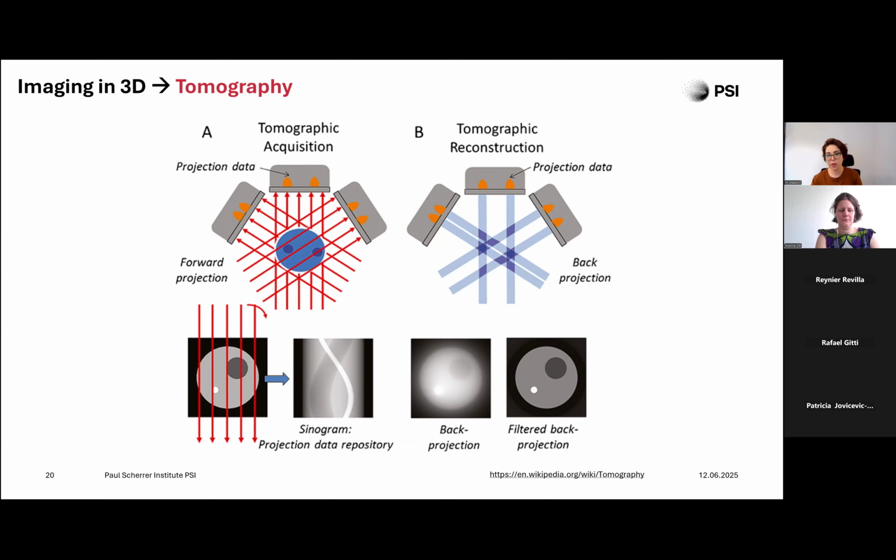But in filtered back projection, we first pass each projection through a high pass filter to correct for the fact that if we did just simple back projection alone, as you can see in this figure, we would overweigh the low frequency components. Once filtered, we can smear each profile safely back across the image volume along the same angles at which the projections were acquired.